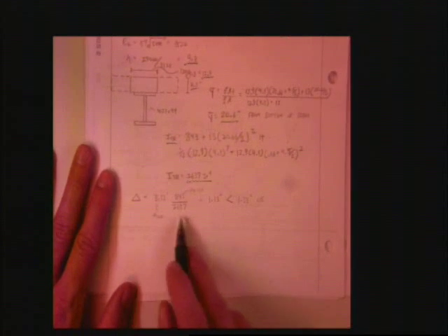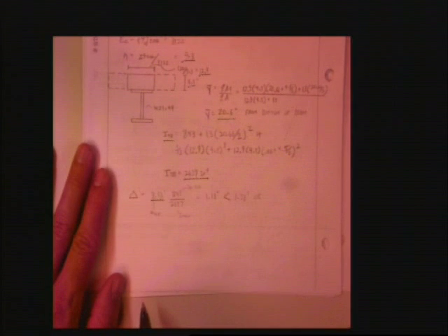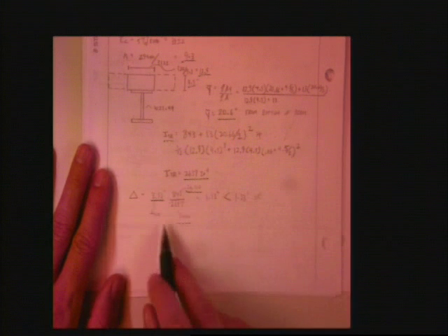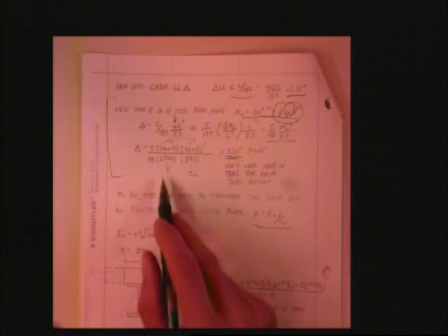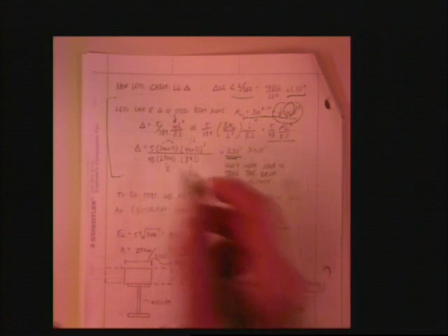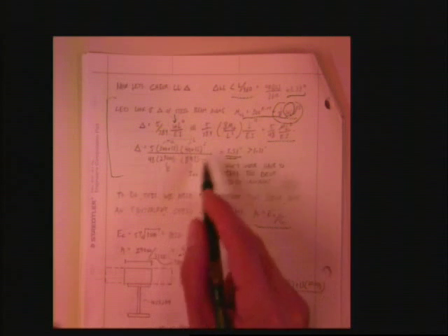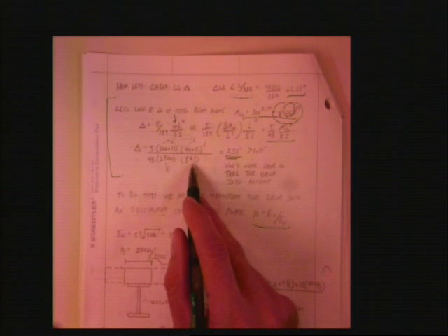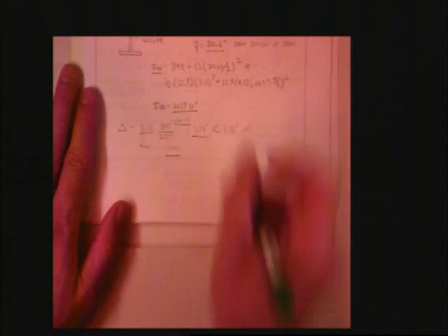So all I did here was, instead of going back and calculating all this stuff before, I just ratioed it. Took my old deflection, I ratioed my old I by my new I. If you don't like this, you can redo this entire calculation using the correct I. If we notice, everything in here is a constant. That's what's different. Okay? I'm just ratioing them, saving myself doing math. And I get 1.13 inches, which is okay.